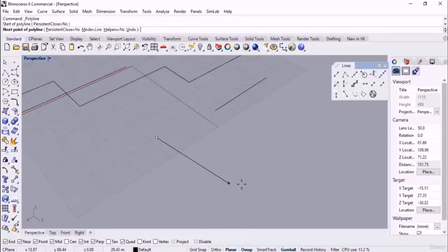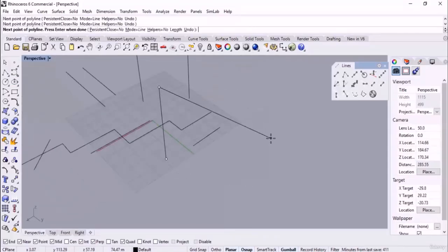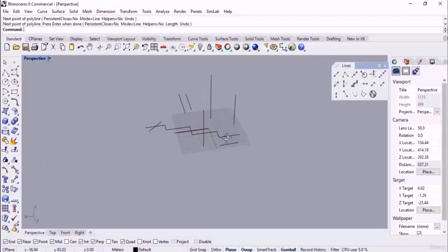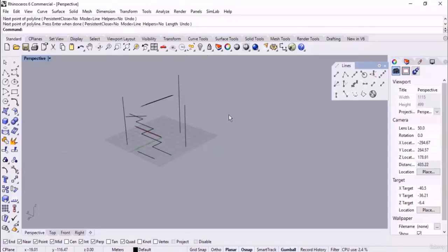Here you may ask what is the difference between holding down the control button and using vertical line from C plane, since both of them give us a vertical line which is perpendicular to the work plane. I should say that we can use holding down control in other commands too. You're obliged to learn both of them, and in the future sessions you will get familiar. All in all, we got 3 approaches for sketching a vertical line that we should learn.